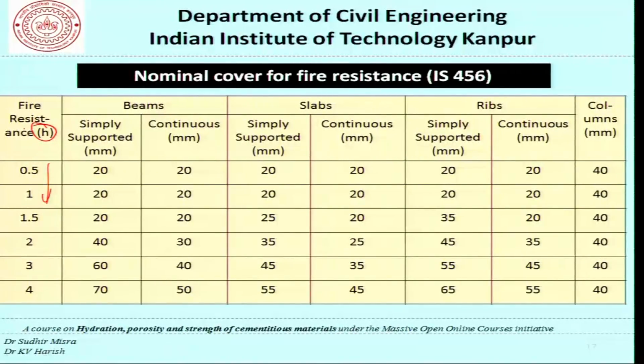longer duration. And without getting into the details, this time here in the first column depends on the kind of structure that we are talking about, its functional use, and the amount of combustible material likely to be stored and so on. And we can see that the cover depends not only on the time of this fire, but also on the members, the beams, the slabs, the ribs and the columns, and what the support conditions are. So, this is governed largely from structural considerations and the fact that we want to protect the reinforcement against an